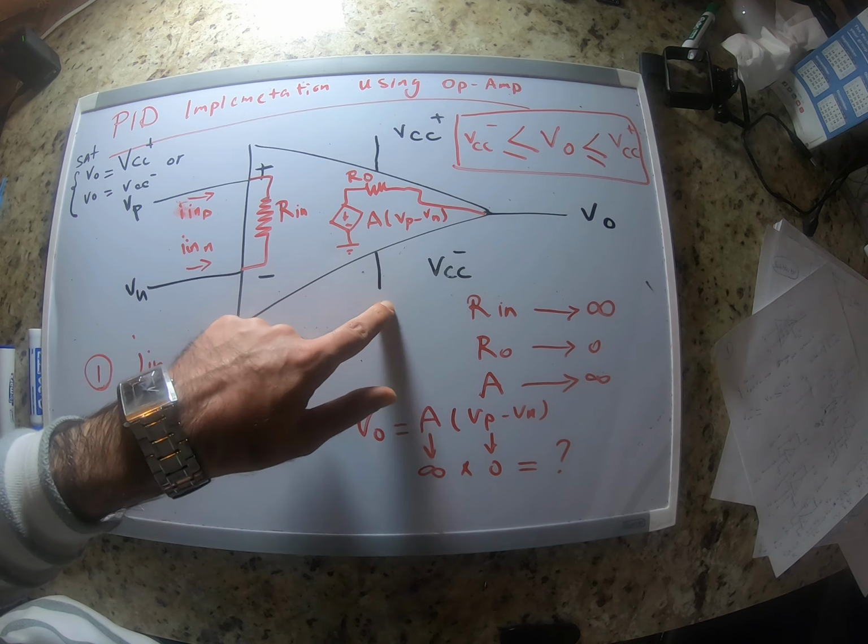If you have negative feedback, on the other hand, it's the same concept that we have in control. Once you have negative feedback, then basically op-amp can keep track of the difference between these two and tries to minimize their difference, the delta V, which is the difference between VP and VN.